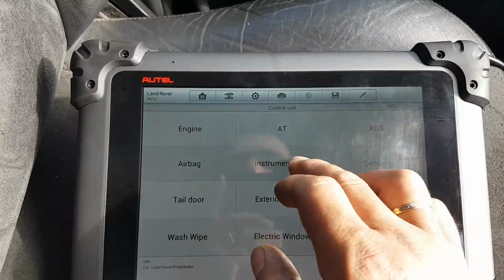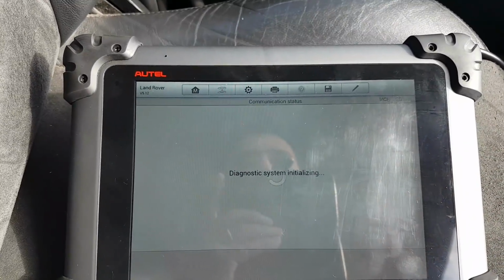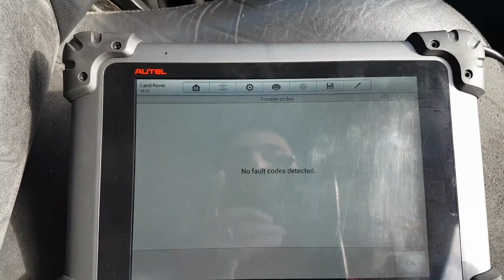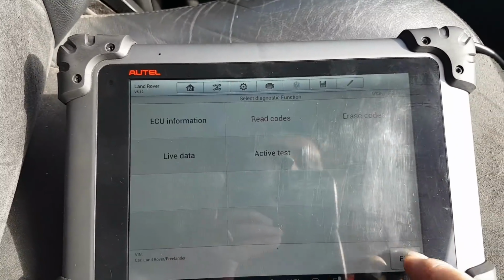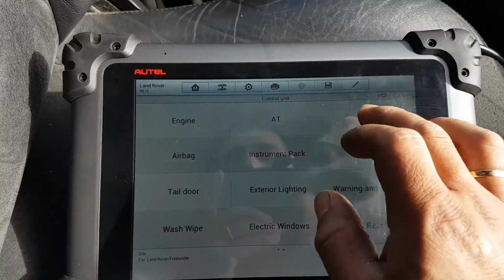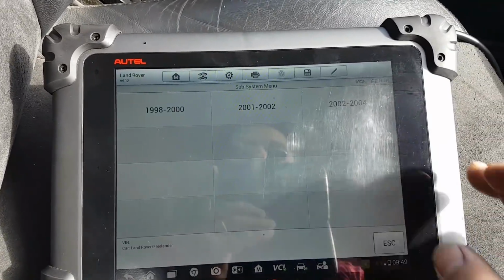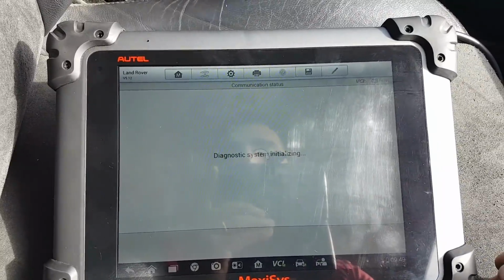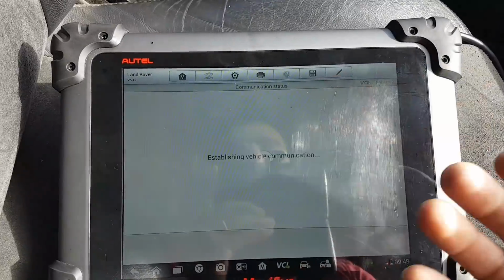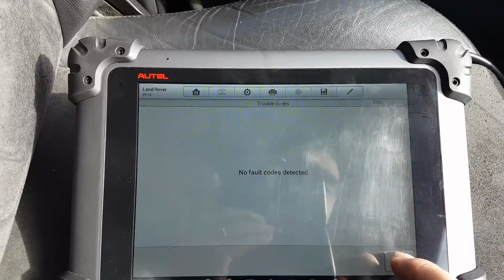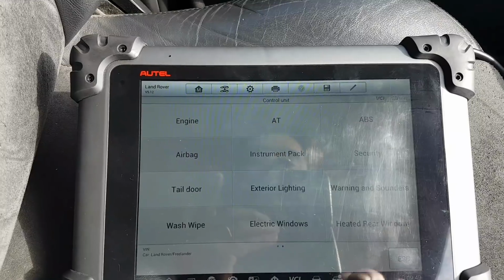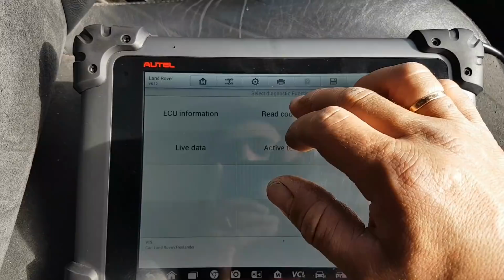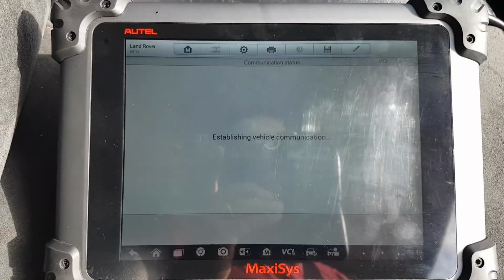Because to be honest, the gearbox seems to be just doing what it's supposed to do. It's just the fact that the engine is not giving the output, so the gearbox can't. So no codes in there. That's why I've deleted all the codes before, because with all the codes that were in there, you never know which ones were there earlier, especially with no freeze frame data. Okay, so the only code we have coming back is that one. It's on the engine and is a pre-fuel delivery.